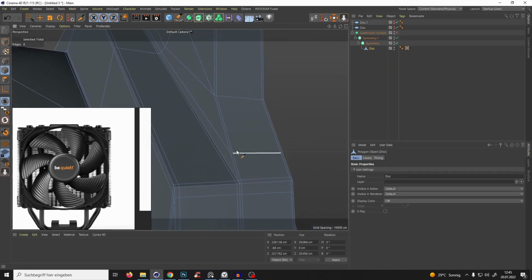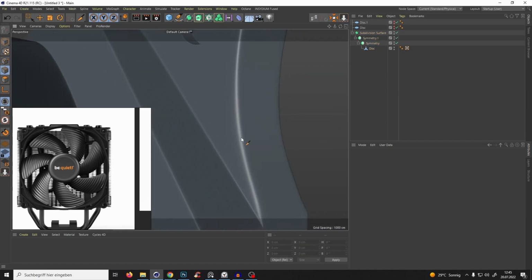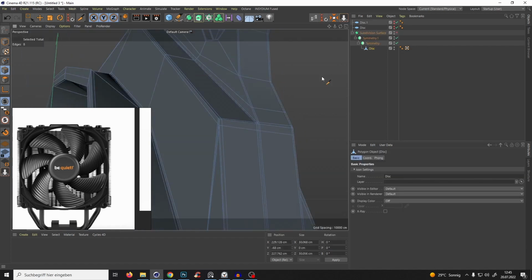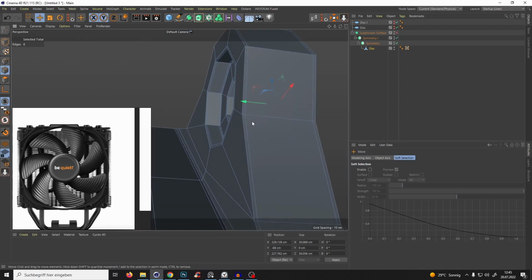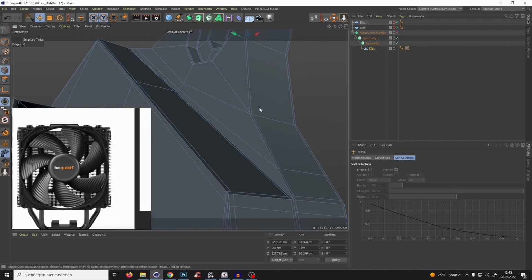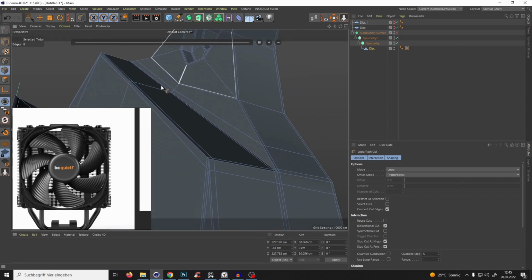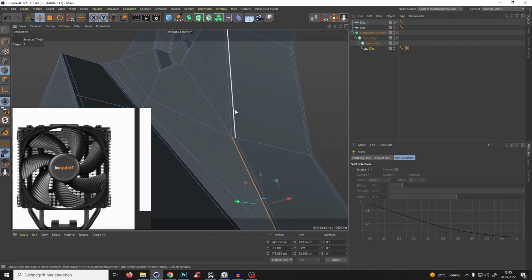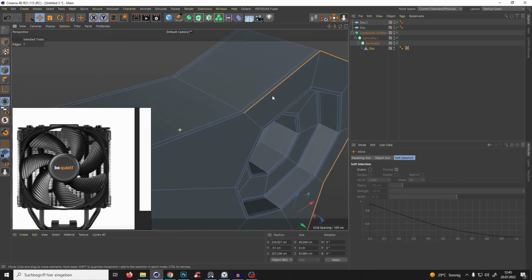in that case it's enough, because what we are missing here, you see those edges, those are harder than this edge here. That's because if we go to the topology, as we did before, we created those supporting lines, one left and one right of the edge we want to make hard, but here we only have one, so we have to add another one. But now it's not looping right, so we have to select those edges here we want to make sharp, again manually, something like that.